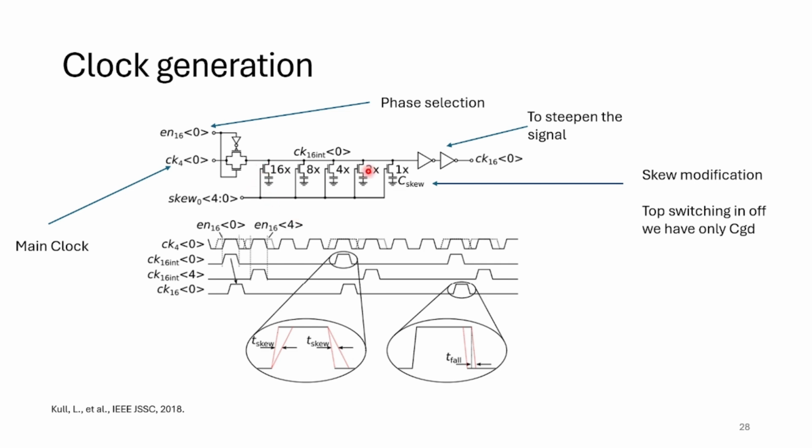The reason is when the switches are off, they have less capacitor coupling to the output, and they would less limit the high frequency specification of the system. However, if we do the switching at the bottom, this capacitor will always exist there.